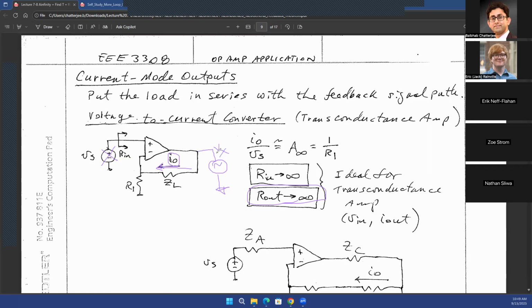Now what you're interested in eventually is that at the output, this is the resistance through which you are calculating your output current, Io, through this ZL resistance, right? But as you have connected this Vx source at this node, what would happen to the current that is coming out of Vx? There is a current coming out of Vx, and all of that current is going to flow into the op-amp if this op-amp is ideal. If the op-amp is ideal, all of that current will flow into the op-amp and go to ground, because the output resistance of the ideal op-amp is 0. So there will be no current going through the ZL resistance.